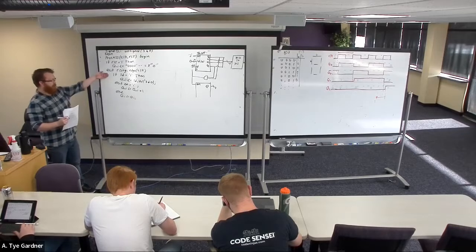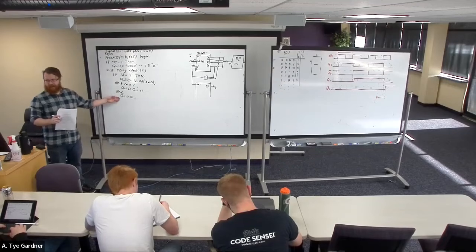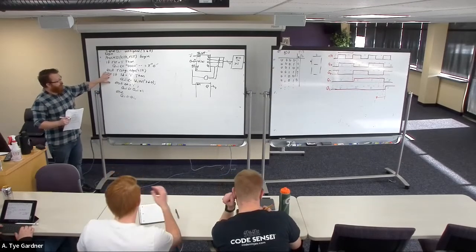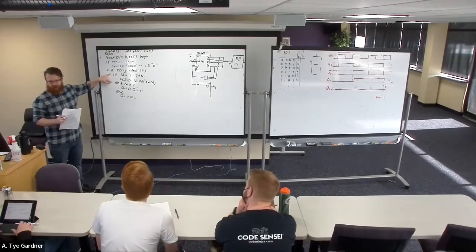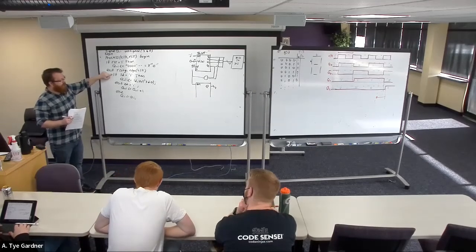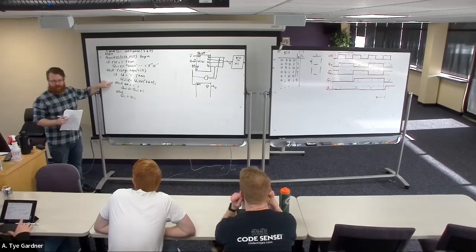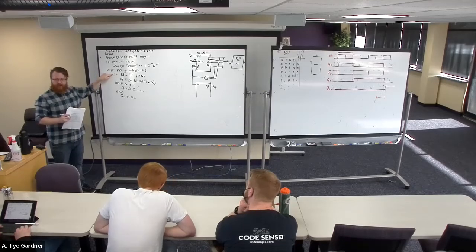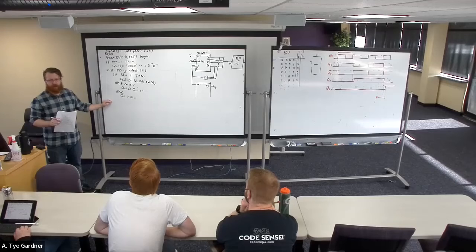So if we're load, then load. If we're enabled, count up. Otherwise, stay the same. If you flipped load and enable, you would have a potential problem, which is that if enable came first, then you can't load unless you're not enabled. Because if the first if evaluates, it won't look at any of the other portions of the if statement. It won't look at any of the else's.